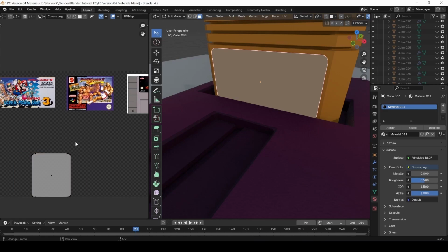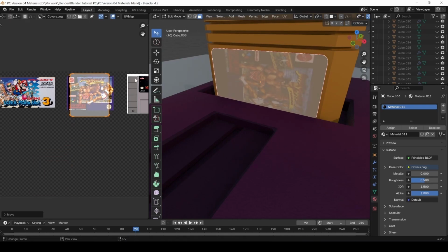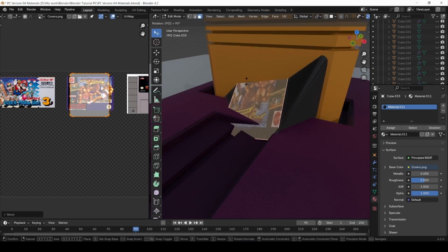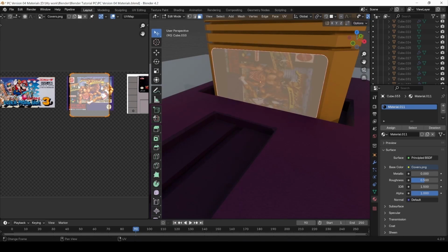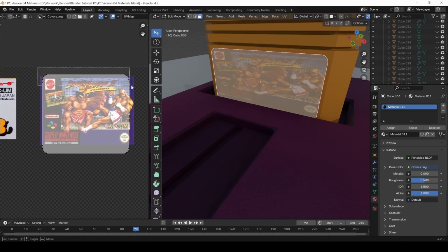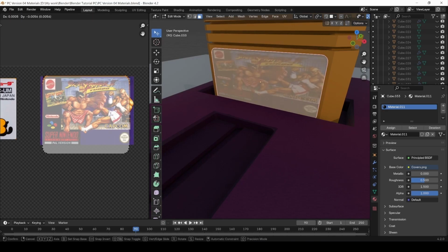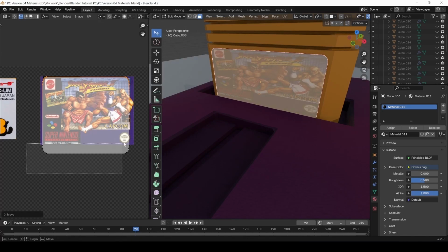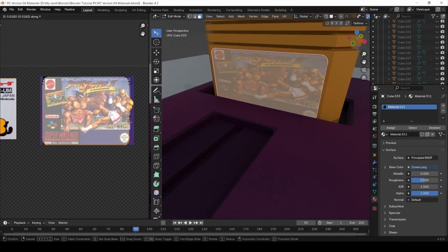Okay, so what we are going to do now is take this, which is this, and put it here to have this as a top. So press G, put it right here, and you can see it's rotated. So let's rotate 90 degrees. No, not here, but rotate it here. R minus 90 degrees. No, R 90 degrees. There you go. And now all we have to do is basically choose all this, go to 1 to 4 for this. Be sure this is disabled, and just J and Y to move it.